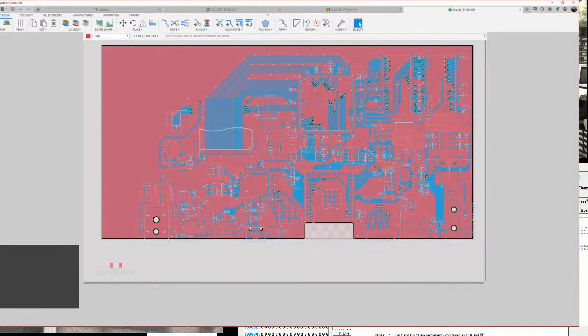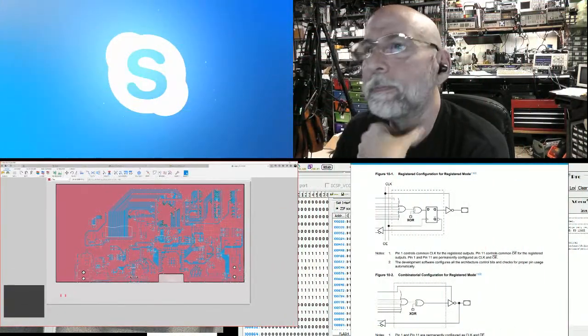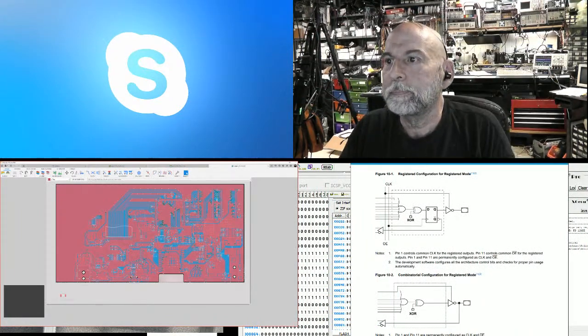So if I go back to the schematics, I modified the schematics a bit through the week because I got a little confused over the power supply requirements, because one reference design that uses this part has a chip that has this, and I realized there's 2 variants of this FPGA that have different power supply requirements. One uses a core voltage that can be 2.5 to 3.3 volts. Right. And the one on the breakout board has a core voltage, in the schematic of the breakout board, at 1.2 volts.